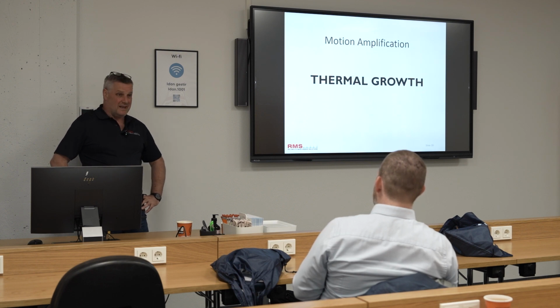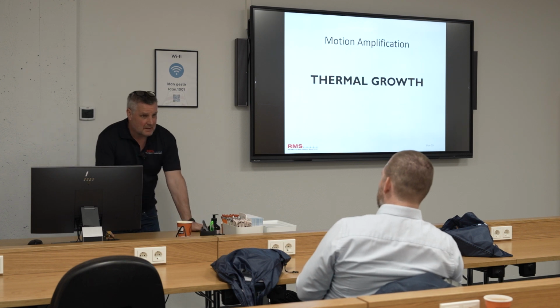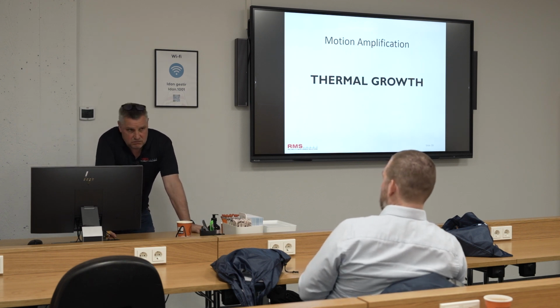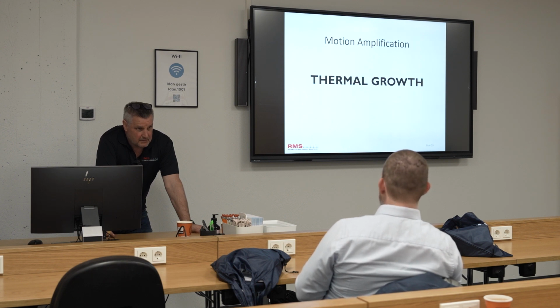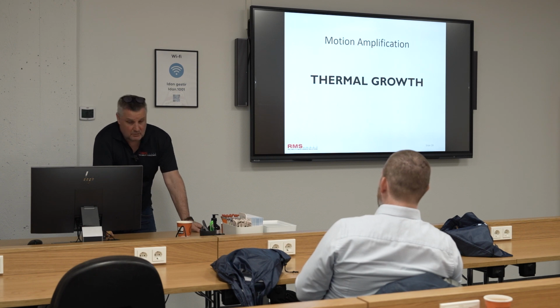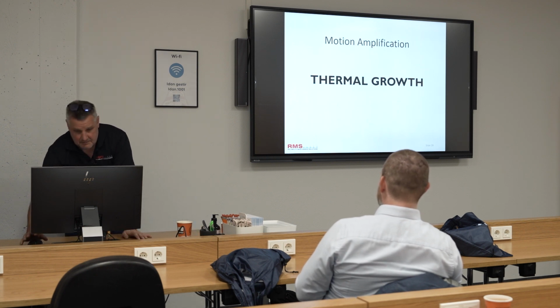We use 10816-3 for normal equipment and 7919-3 for turbines, for displacements and measurements like that. But they've been there years and years and they've never been upgraded. And 10816 upgraded to 20816 just recently? I believe so, but I don't think we're using that at the moment. But I think it may well be, though. It needed to be, to be honest.